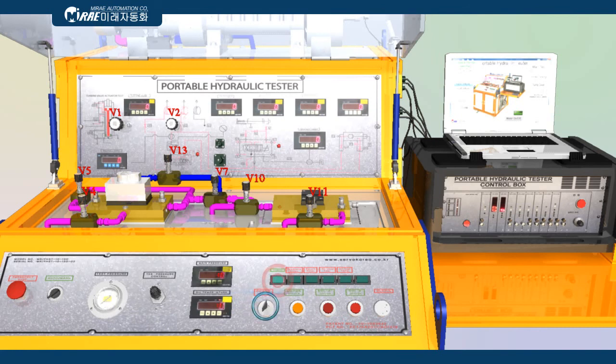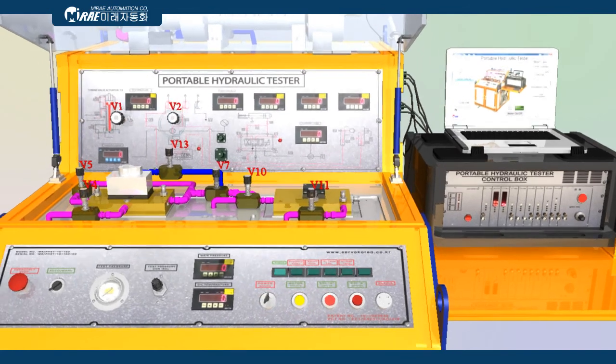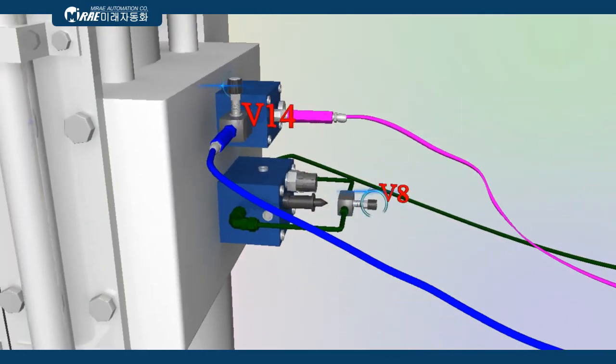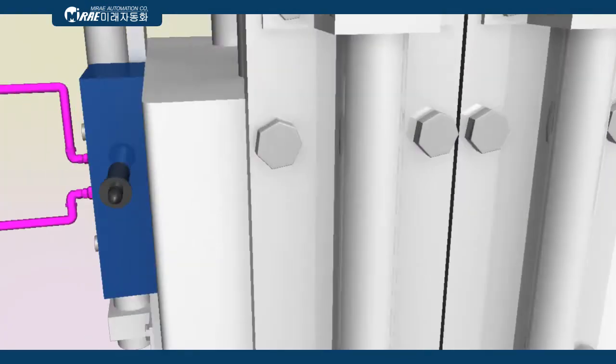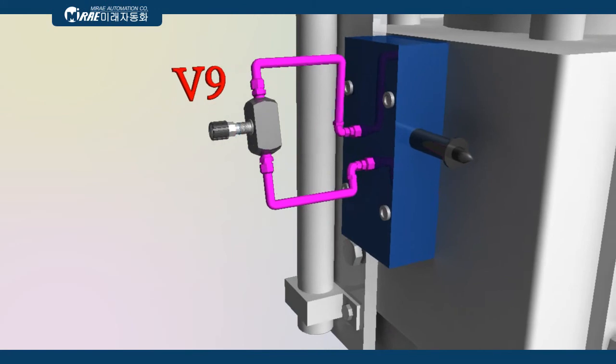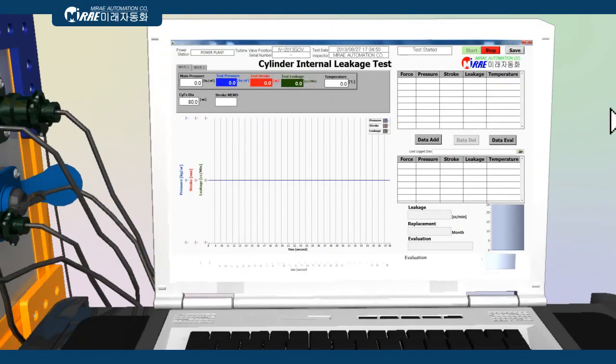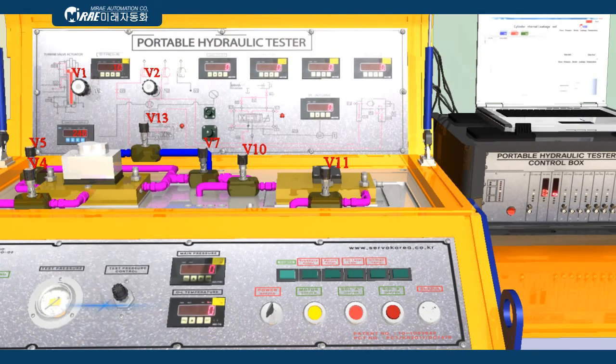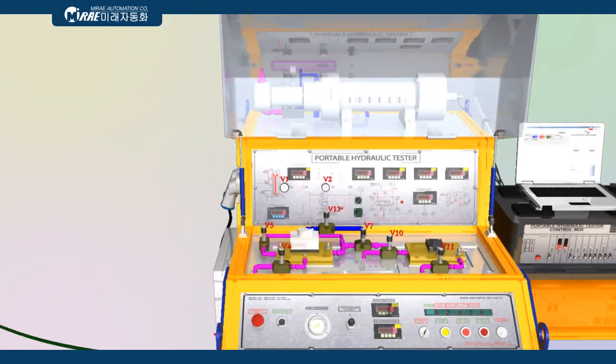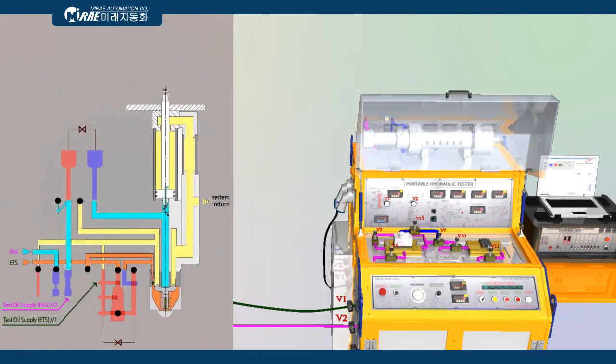Turbine valve actuator tester measures the oil pressures, leakage flow rates, and displacements, and analyzes the data and applies repair and replacement period estimation algorithms automatically. So we can test steadiness evaluation by forecasting diagnosis and produce a test report and the history of performance diagnosis for improvement of management effectiveness.